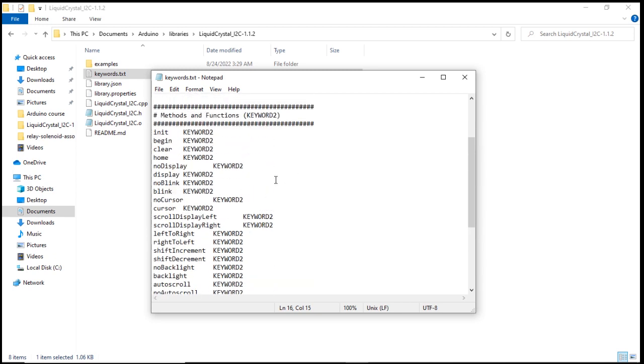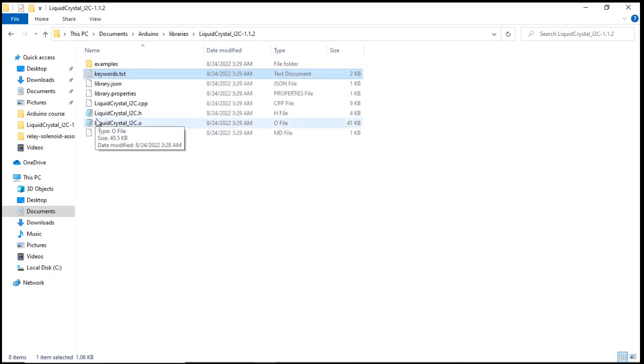So whenever you call any of these functions in our Arduino IDE, the compiler will see where we got those functions. So whenever we do #include with .h, this is what we are including. This is the header file. That is why you are seeing the extension h. So whenever we include LiquidCrystal.h, the compiler will come here to include this. This is what is being included.